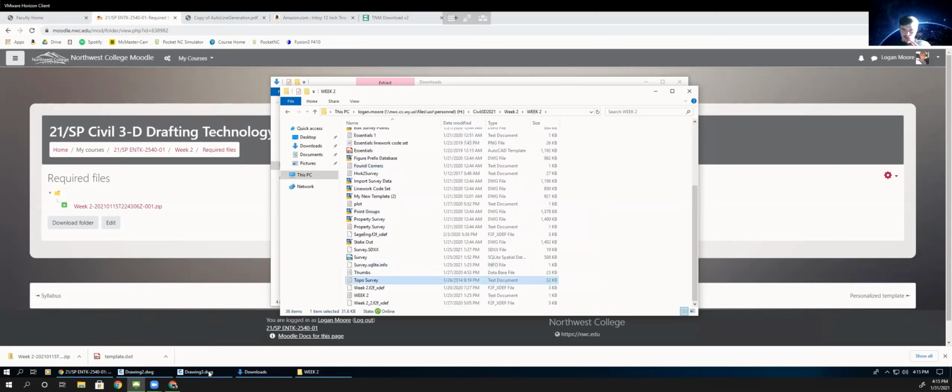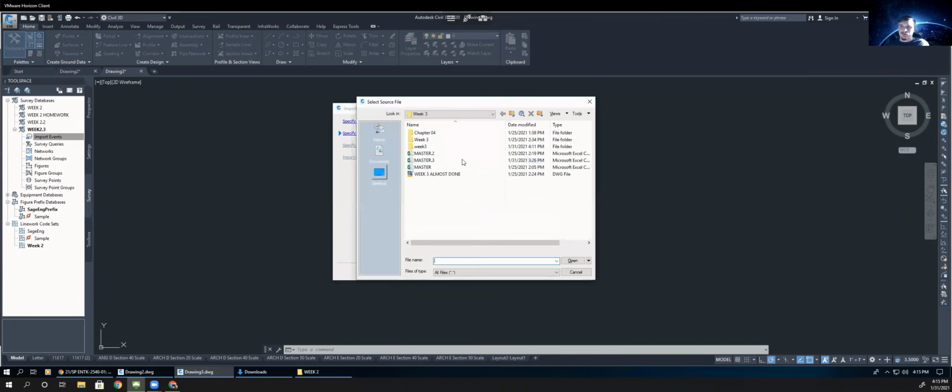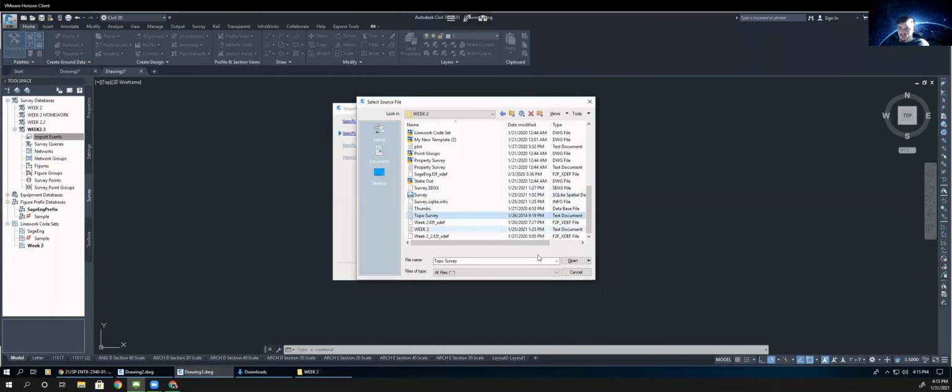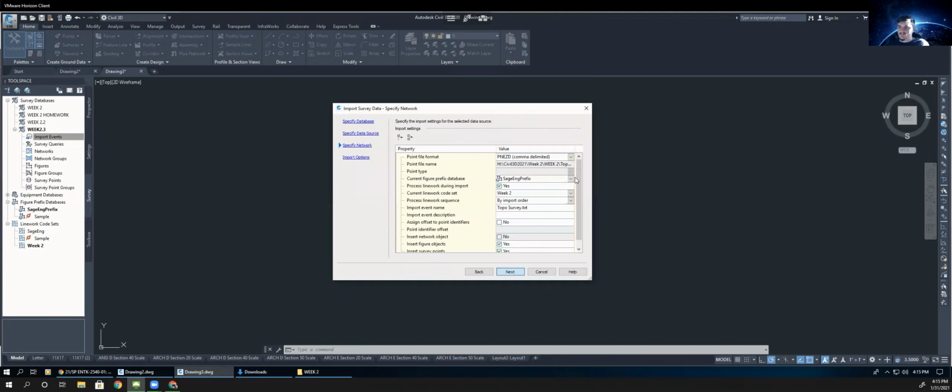All right. So go back into the import survey data window, hit this plus to browse, and then we want to go back to week 2. Week 2. Week 2. Topo survey. That's the one we're looking for. All right. Hit open. And then you want to make sure that you have PNEZD selected, or else your points won't import correctly. So then hit next again.